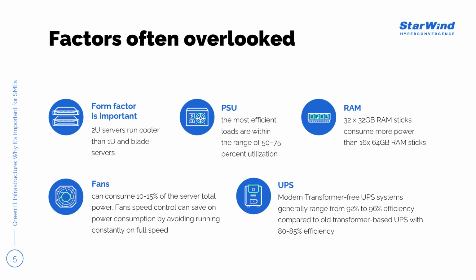So for example, your planned 50% of workload that your power supply unit should hit to reach that sweet spot of highest energy efficiency will actually be 25% on each power supply unit, leading to their lower efficiency. Again, that won't be a problem with the higher ratings of platinum or titanium, but this will be a problem with older power supply units or units with lower ranking, such as bronze, for example.